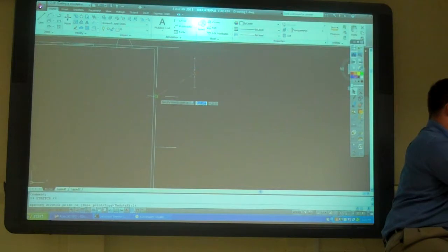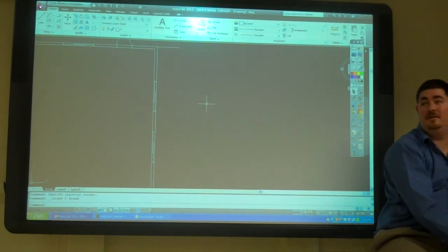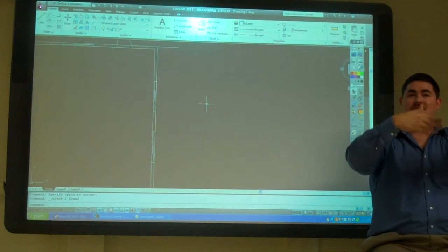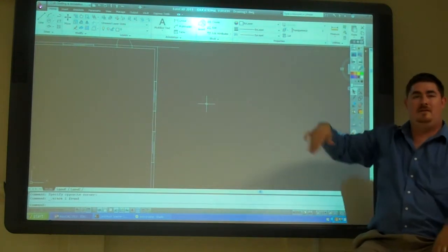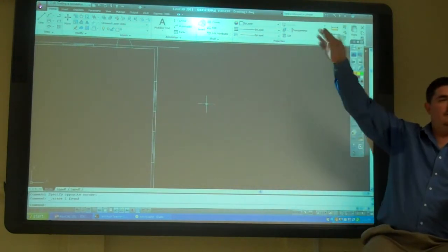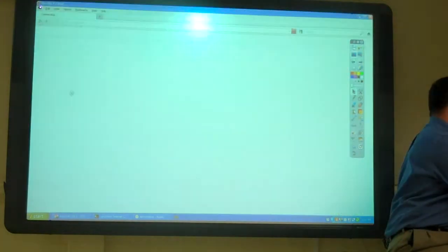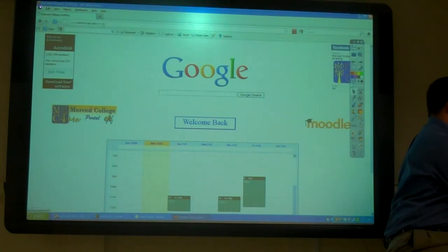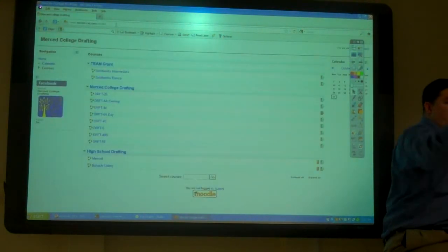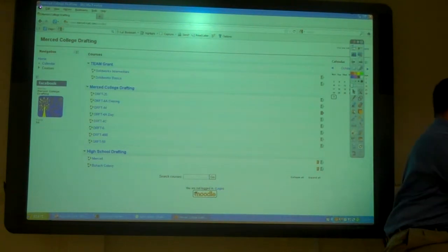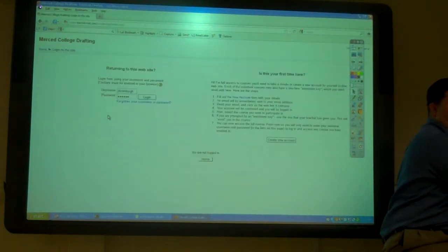And I can just grab that, move it there, copy that from there to there, erase it. Because in architecture, they actually dimension from one to the next, so you don't always get the measure from the end. So you can just draw a line, offset, offset, offset, offset. Can you actually just grab it, take it to the corner and get the? You could, but then you have to do that for all of them. Or you could offset a bunch of lines and then just copy them. Kind of doesn't matter how you do it.